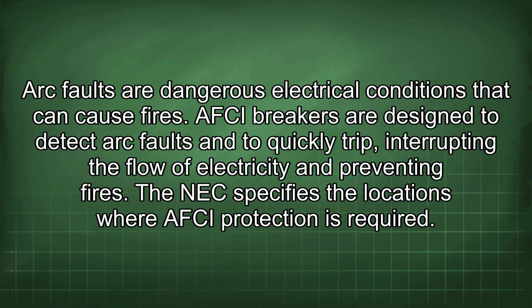Arc faults are dangerous electrical conditions that can cause fires. AFCI breakers are designed to detect arc faults and to quickly trip, interrupting the flow of electricity and preventing fires. The NEC specifies the locations where AFCI protection is required.